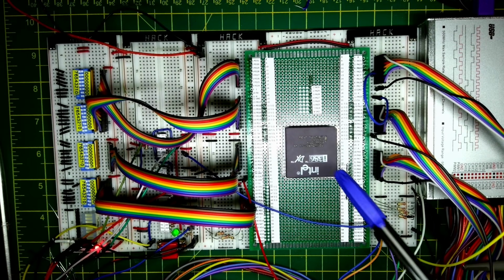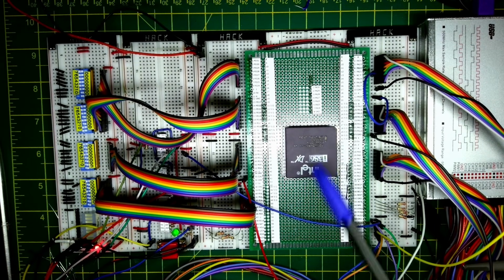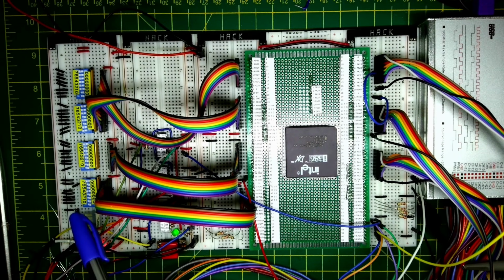So we've managed to test our 386, at least it's sort of responding to the clocks and reset, and we're able to show that a very, very simple program from these dip switches is actually running. In the next video, I'm going to be looking at seeing if we can make something slightly more interesting in these 4 bytes that we've got for writing a program, probably one of the world's smallest programs. So I'm going to be experimenting with a couple of options to see if we can get a bit more activity off the address lines using some 4-byte programs.